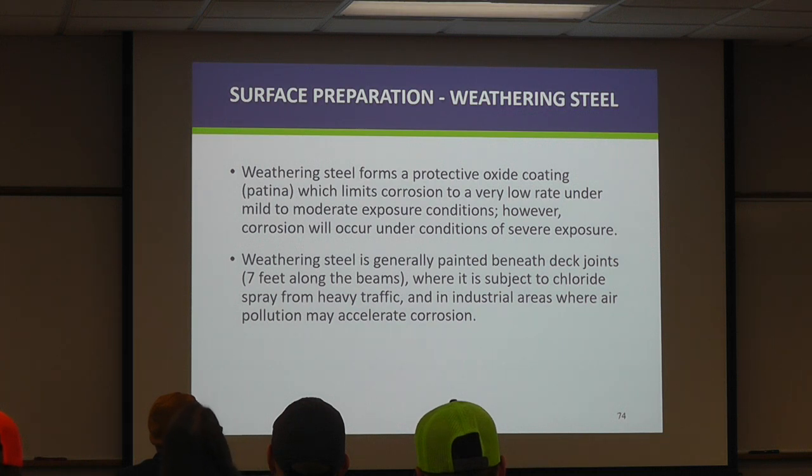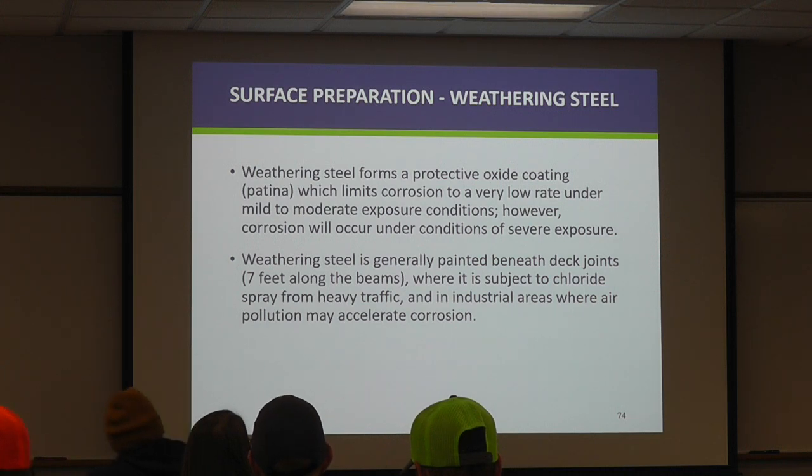Weathering steel in the wrong conditions will rust very rapidly. If part of the job is taking care of some intermittent spots on weathering steel, it's usually beneath your deck joints, joint ends or abutment beam ends, 7 feet out along the beam. That's where you get most of your chloride infiltration.